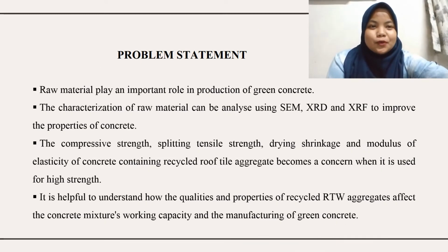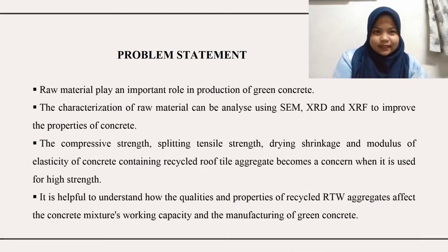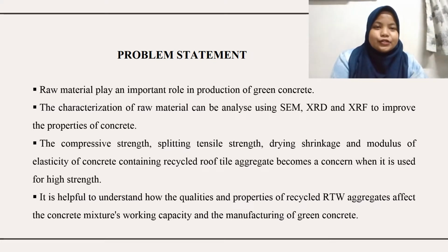The most important thing in forming concrete is the mixture of the raw materials. Some analyses need to be done on the aggregates, such as SEM, XRD and XRF. Properties of the concrete become a concern when changes are made in the mixture of the concrete. It is beneficial to understand how recycled rooftile waste aggregate characterization and properties will influence the working capacity.